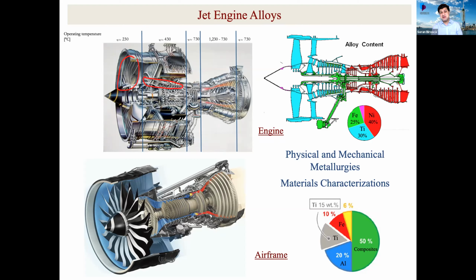And I spent many years working on nickel-based superalloy, which is used on the turbine side, single crystalline and also polycrystalline, like the Rolls-Royce alloys used for the jet engine disc application, which we call the hot side. So this is a very, very hot part of the jet engine. This is the relatively cold part, below 500. That's what we call it.